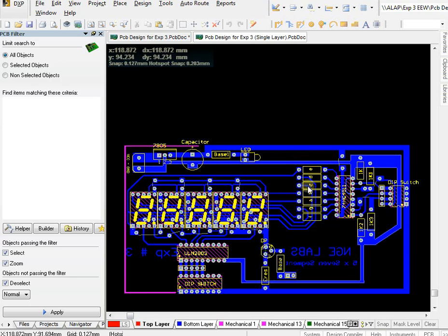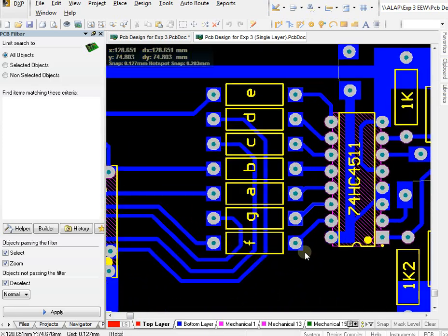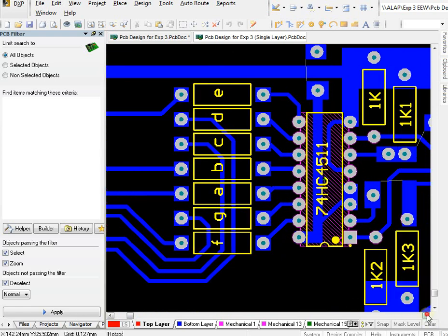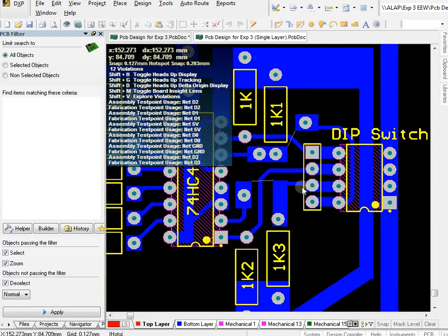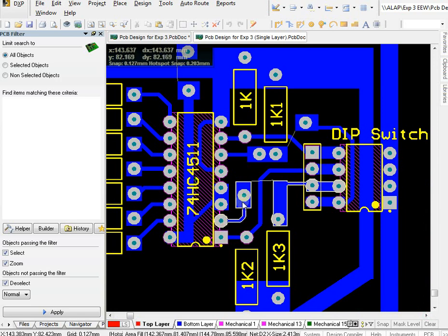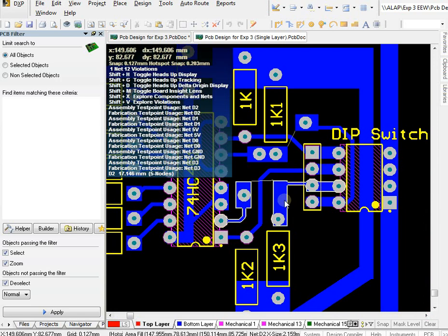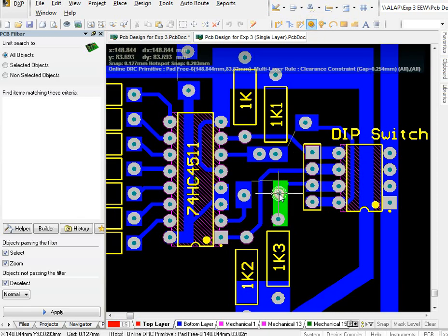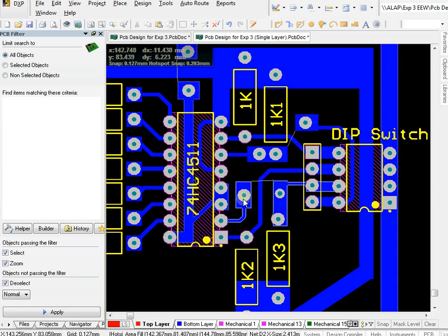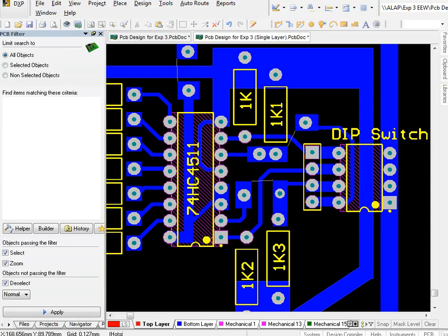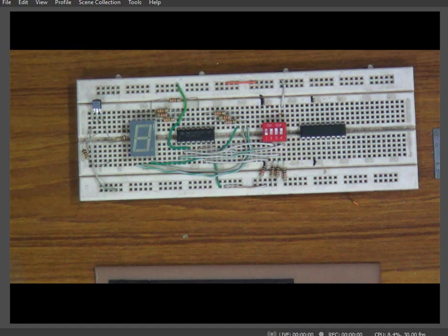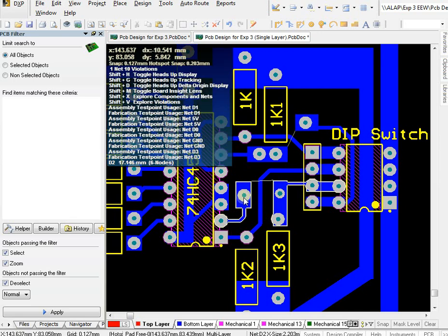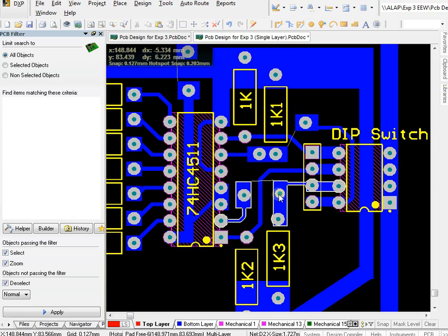Now, as I was telling you, this is not a big problem. This area also not a problem. Why? This was connected and this had to cross from here to here. But what I have done, I placed a fill area, and I can now connect, in fact I have missed one pad over here. So I can connect a jumper, because there is a hole here, I can place a jumper wire just like this one, and I can place it from this hole to this hole very easily.